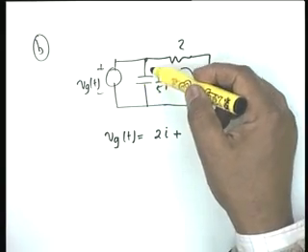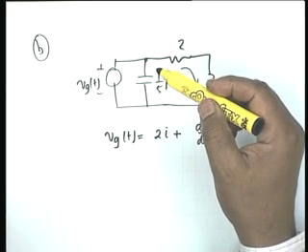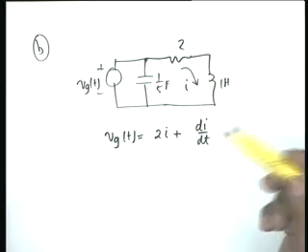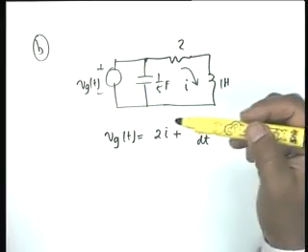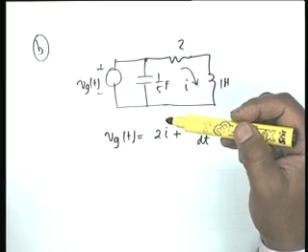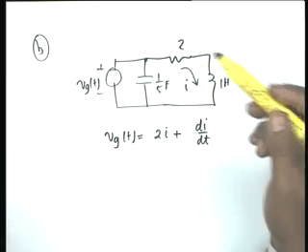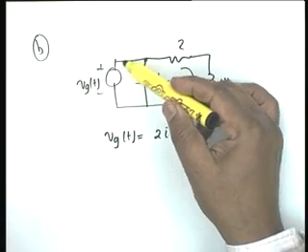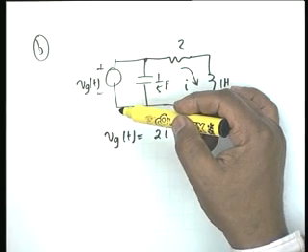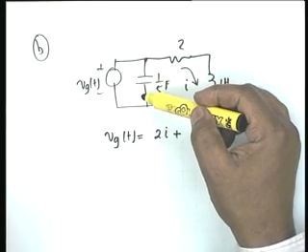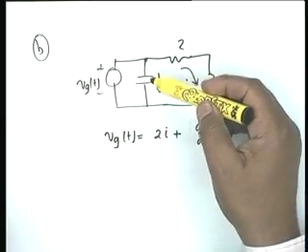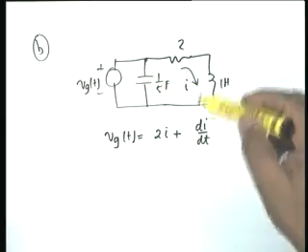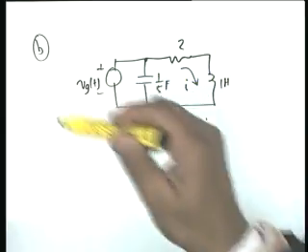The capacitor is ineffective, it does not affect the differential equation or the free response of this circuit. Why not? Because this is a voltage generator. One way to look at it is that the natural response is found by short circuiting a voltage source, which short circuits the 1/5 farad. The other way to look at it is that any element connected across a voltage source cannot affect its voltage.